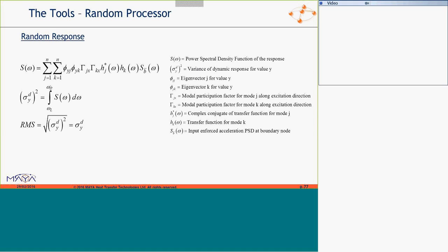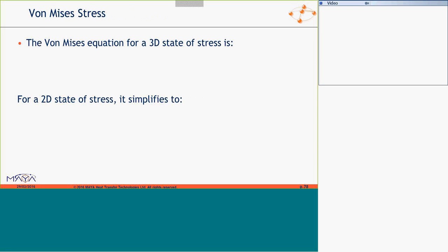If you do an integral like this for each response, you're doing it in a very poor way, because you'll be integrating each response. That's one of the things that we don't do in SA Toolkit. We integrate on a reduced basis, which is why we're so quick. And so we're able to quickly get you not only RMS results, but you'll see the peak results as well.